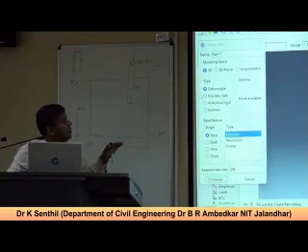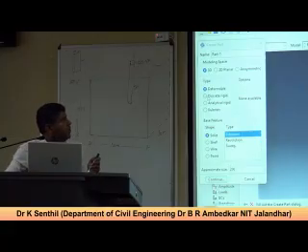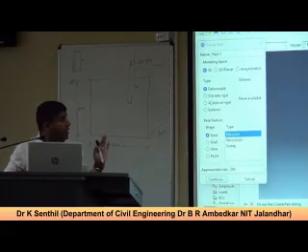Now let's talk about this deformable. Of course, the soil is deformable. But the pile you can treat as rigid. For that you choose any one, either discrete rigid or analytical rigid. So what will this discrete rigid or analytical rigid do?